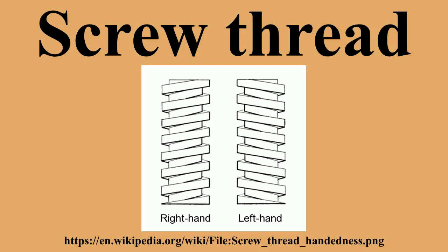Ball screws, whose male-female pairs involve bearing balls in between, show that other variations of form are possible. Roller screws use conventional thread forms but introduce an interesting twist on the theme. Angle. The angle characteristic of the cross-sectional shape is often called the thread angle. For most threads, this is standardized as 60 degrees, but any angle can be used.